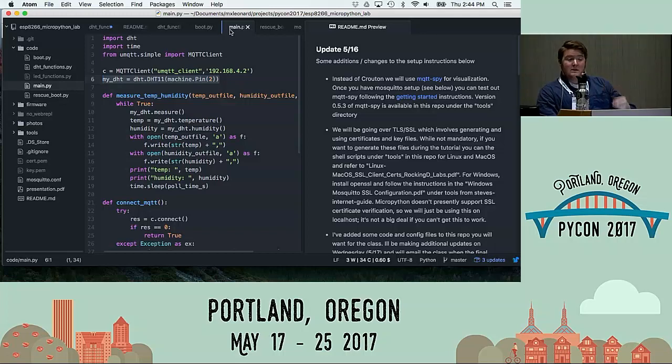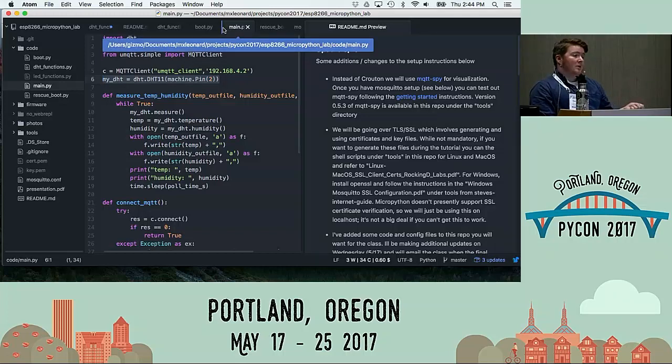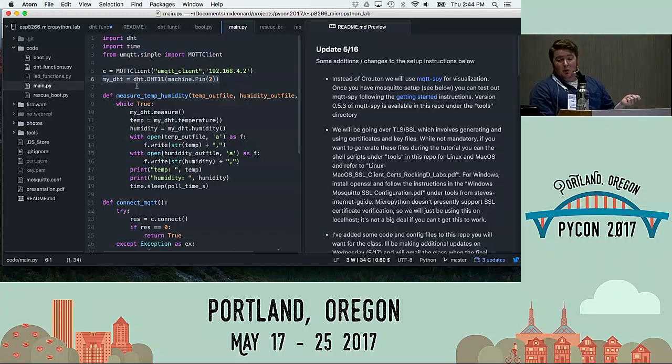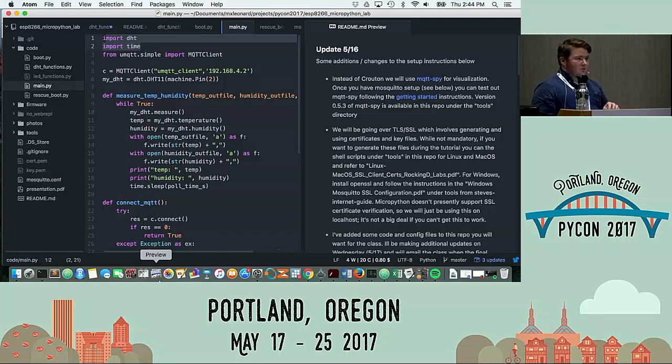So that was kind of the last thing that I wanted to cover in this programming section: if you take your temperature humidity function that you just wrote and put it along with the imports into this main.py file and send that over on WebREPL, then when you reboot the device, your DHT, or if you put the LED in here, all of that will be available to you. You won't have to type any of the code, which is how I prefer to work with MicroPython, because it's, as you are experiencing, rather laborious to try and enter stuff in through WebREPL.